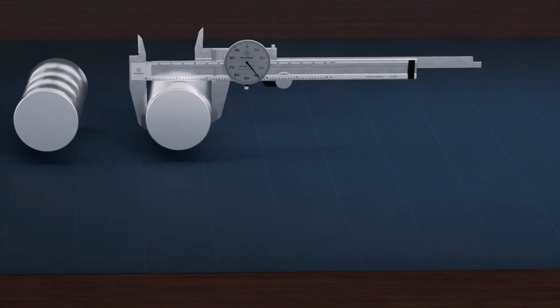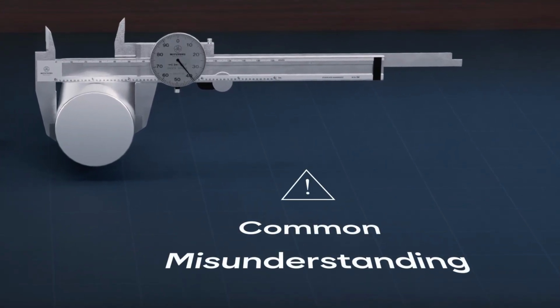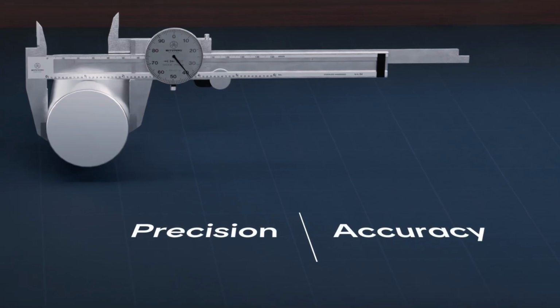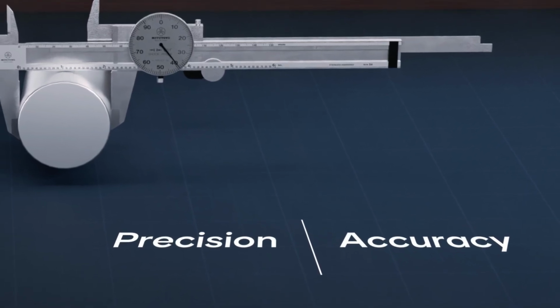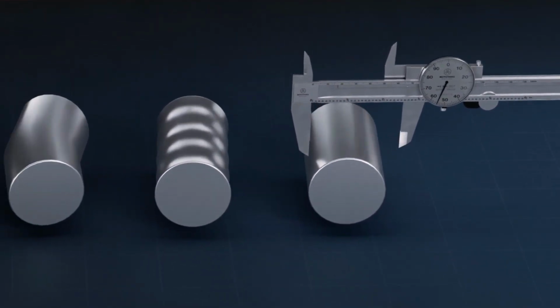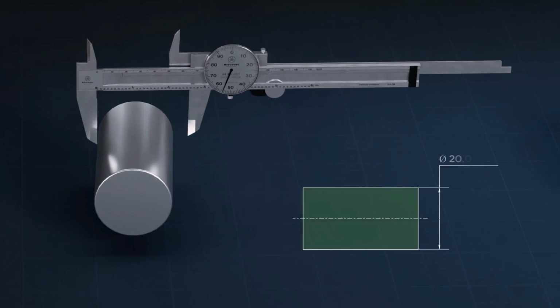Now, before we go any further, we need to clear up one of the most common misunderstandings in quality. Gauge R&R focuses mainly on precision and not accuracy. But wait a minute, aren't accuracy and precision the same thing? And the answer to this question is no. Let me explain with a simple example. Imagine we're measuring a machine shaft with a specification of 20.00 millimeters. Now let's look at three scenarios.